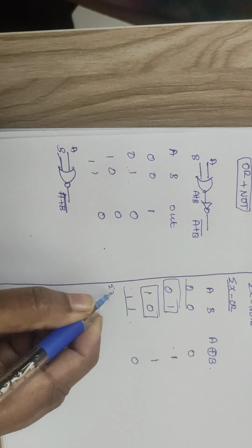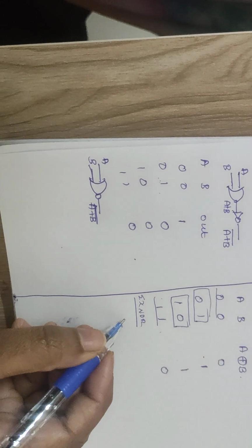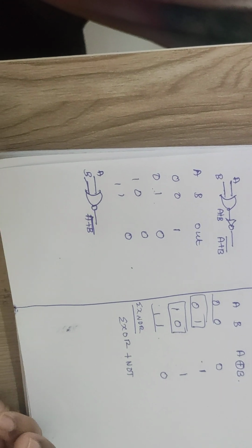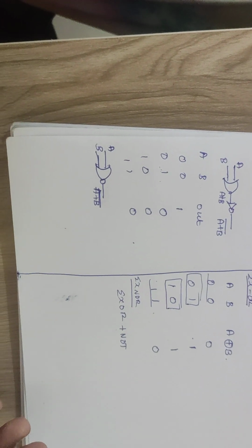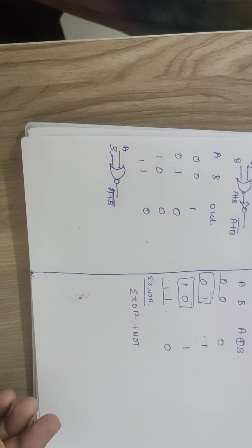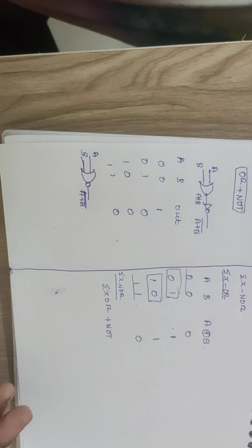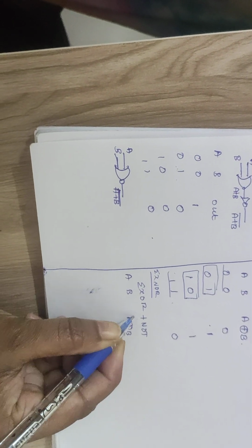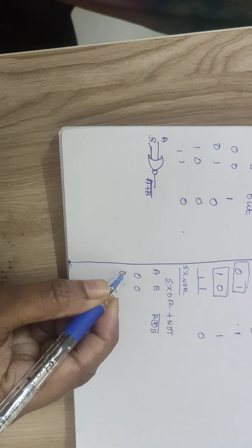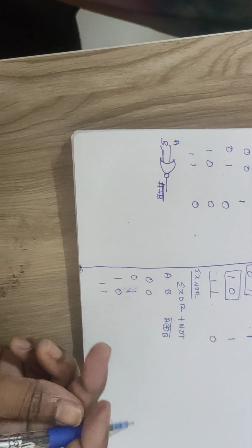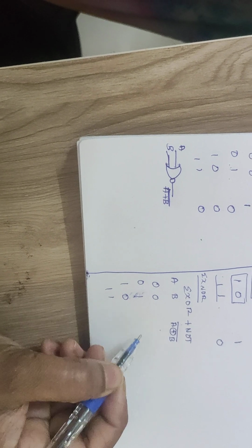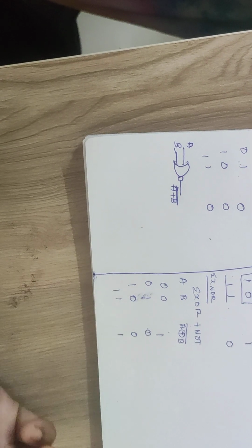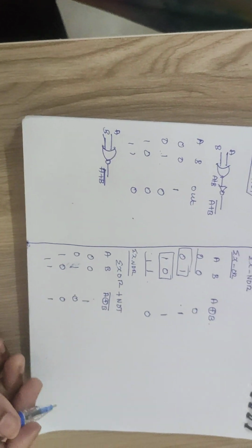In parallel we'll write about XNOR, because XOR followed by a NOT gate is called XNOR, same as NAND or NOR from AND or OR respectively. So here also there is a bar, and we fill in the inputs. You can tell that it is the inverted version. If both are exclusive, we make the output 0, else it will be high. So this is what XNOR is about.